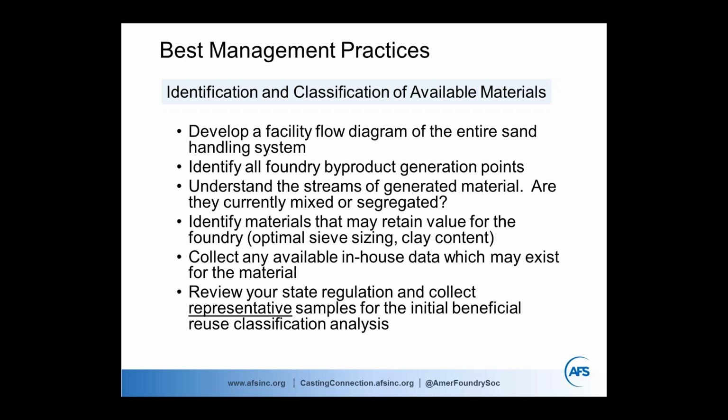There's probably not dozens of foundries approaching your lab all asking for the same type of beneficial use testing. They're very used to somebody coming in and asking for a TCLP or something of that nature. Make sure they understand that if you're doing an ASTM water leach or whatever it might be that your state requires, that they understand the appropriate method and they're doing that test.